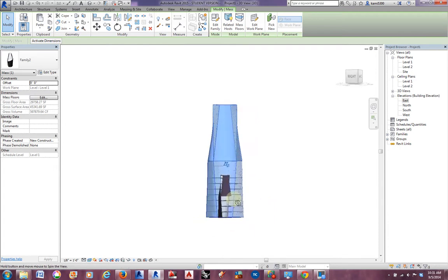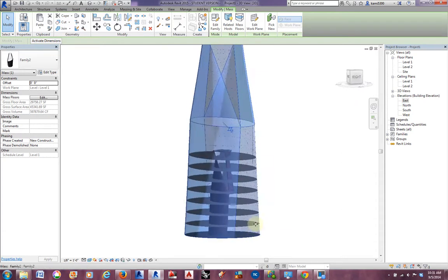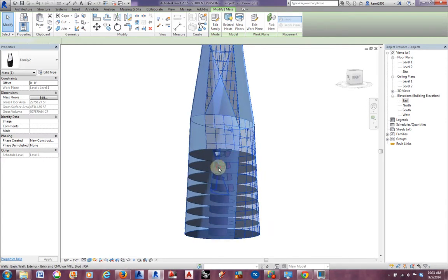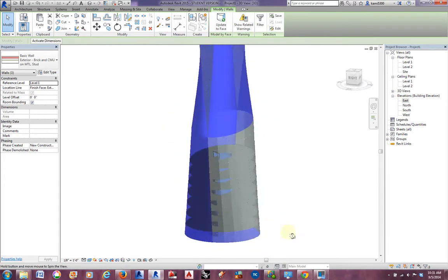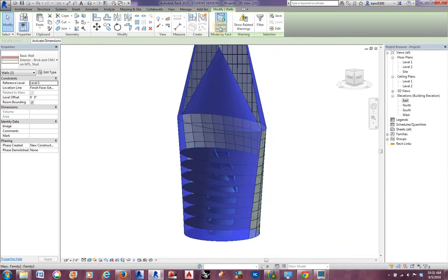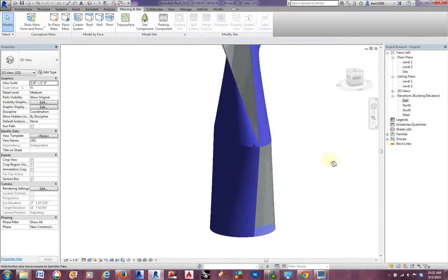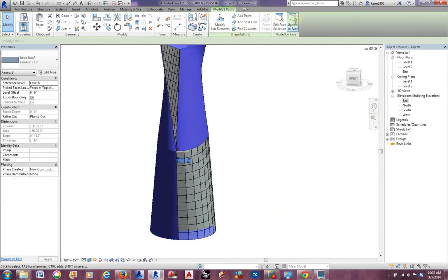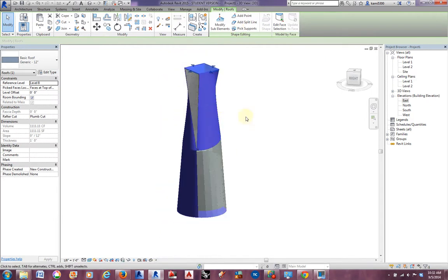Okay, I'm back, and you can see that all the stuff that we just made isn't applied to the mass anymore. It stayed the same except for our curtain walls, and we don't have a ton of floors in here, but again, we could create more floors. But I wanted to show you that if we selected those three walls, we could update to face. And so now those walls are back to being the same size. Same with the roof, update face, it moved it and changed the size of it.